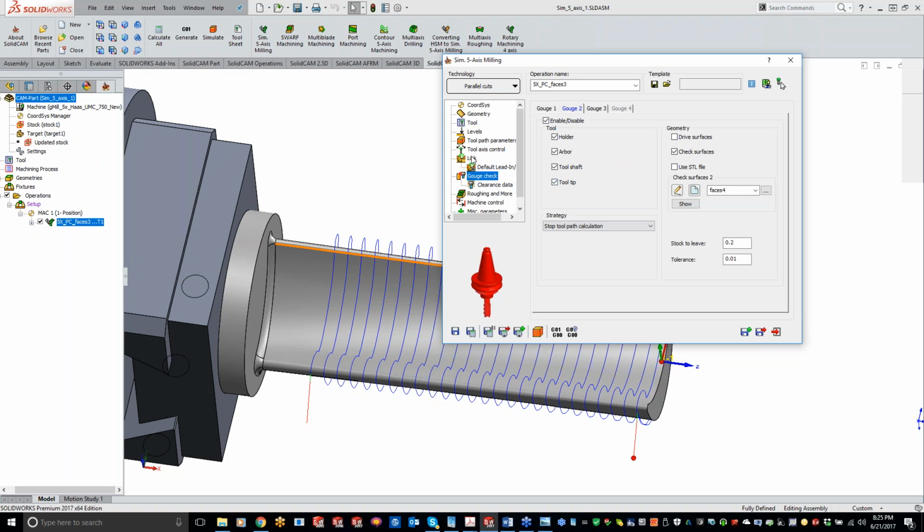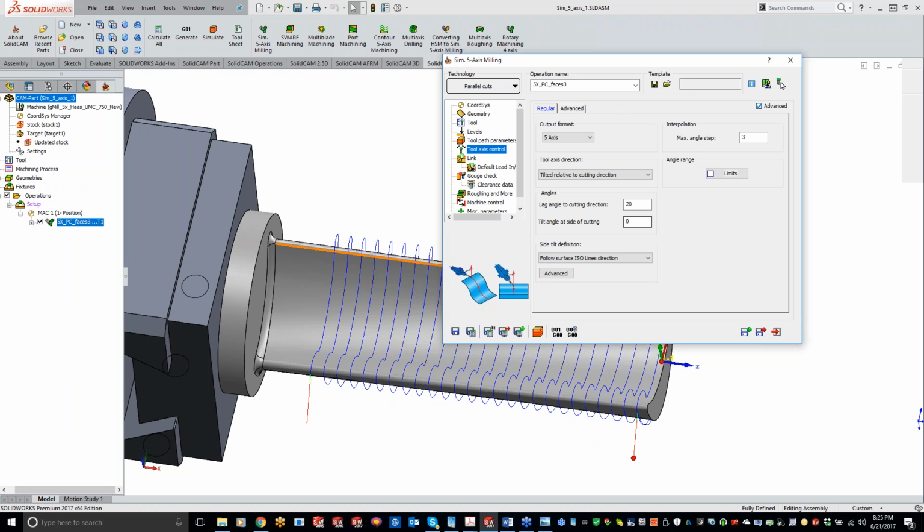Okay, so now I think I can get in there just a little bit deeper if I tilt my cutter off, let's just say 20 degrees also. So let's just kick our cutter over. So now we're working on the ball, but we're leaning off to the one angle. So let's just save and calculate here.